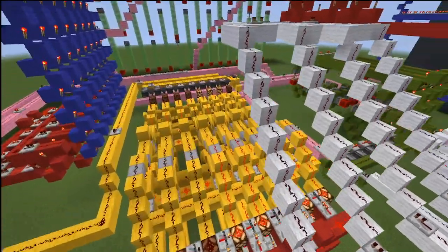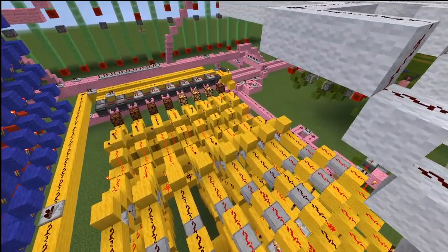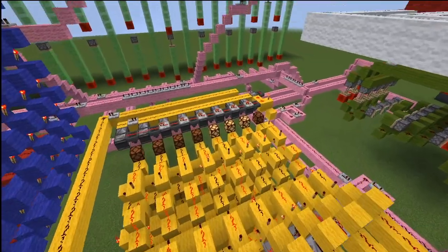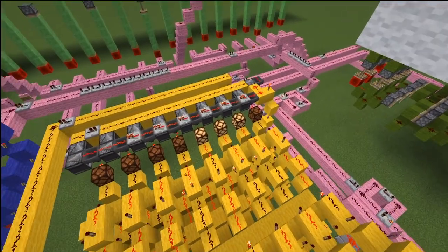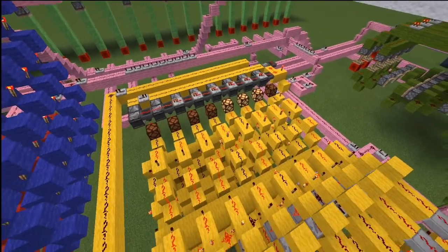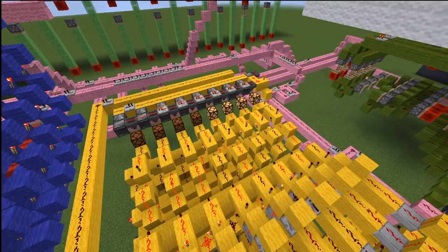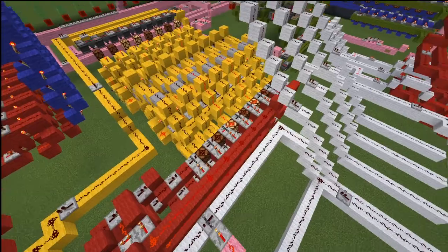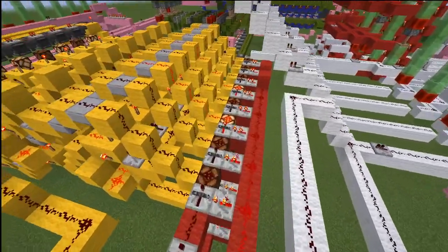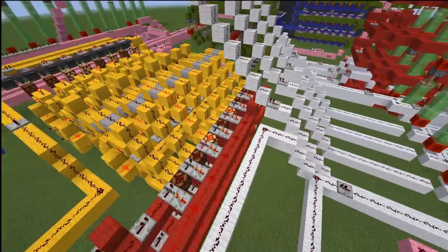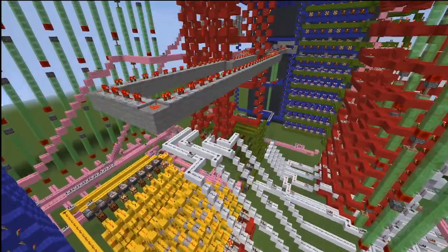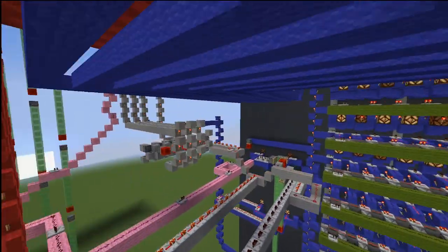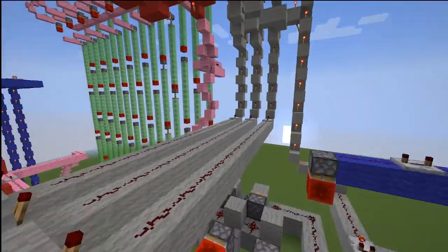And then on the next clock pulse, it's going to change this from subtraction, because right now it's in subtraction mode. It'll change it to addition mode. And then while it's in addition mode, it'll happen almost instantly. Right after it switches to addition, it's going to store that result and send it to the A register, which it just did. And so now that result that is 40 is stored in the A register. And then, so now we can go to the next clock pulse, and that was the add macro instruction.